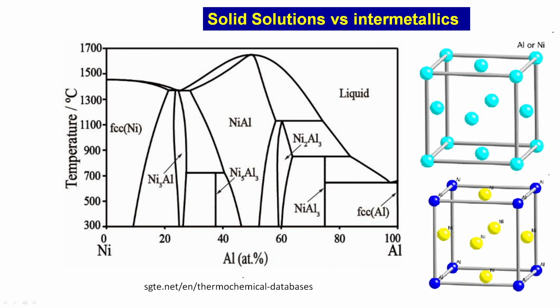You can also have tetrahedral voids, which I have shown you for the diamond cubic structure. Please go back to my lecture number 4, you can see diamond cubic structures. Now, these are the solutions. You have substitution solutions, or the interstitial solutions. There are 2 types of solutions present in these kinds of systems, and I have shown you both. Carbon in iron forms an interstitial solution, because carbon goes to interstitial positions. Interstitials means the locations where there is free space available, like octahedral voids or tetrahedral voids. On the other hand, nickel in copper forms a substitution solution. Similarly, if you add nickel in iron, it will also initially form a substitution solution, with a small quantity of nickel.